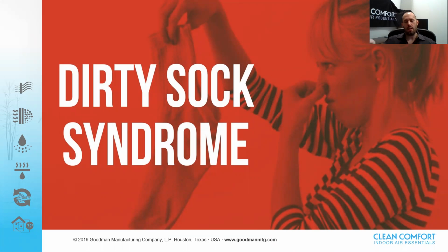Now, this is where you walk into a space and it smells musty, it's damp, it's dingy. And what I can tell you is that the owner is going to say, hey, I've got mold. I know I've got mold because I smell it. And what I would tell you is that usually they're wrong because usually it's bacteria. More specifically, it's bacteria on the coil, the HVAC coil.